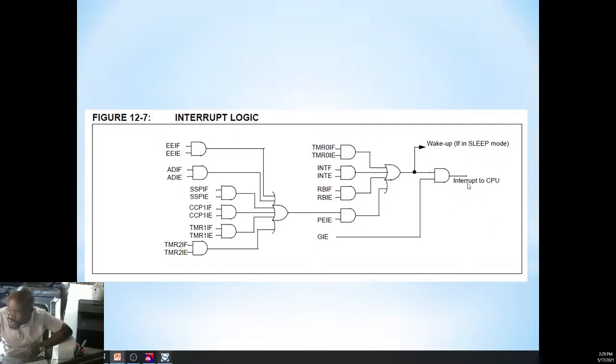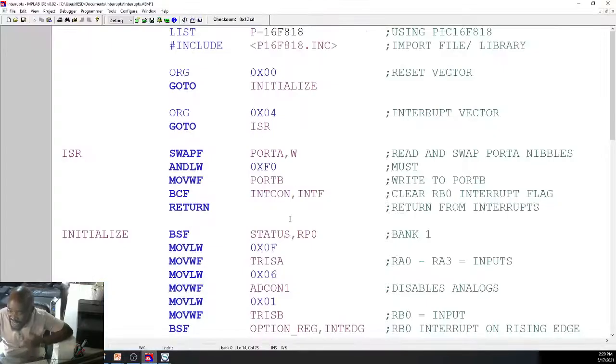Interrupt happening while you're in the interrupts, right? So when CPU disables that GIE when it goes to the interrupt, when you return from interrupt, you need to set that GIE. And now the return from interrupt instruction does that for us. Hence, we have to use the return from interrupt, not just any other return. That's the purpose of that return instruction.